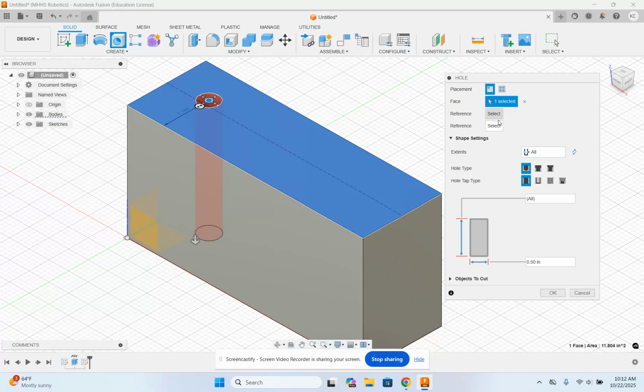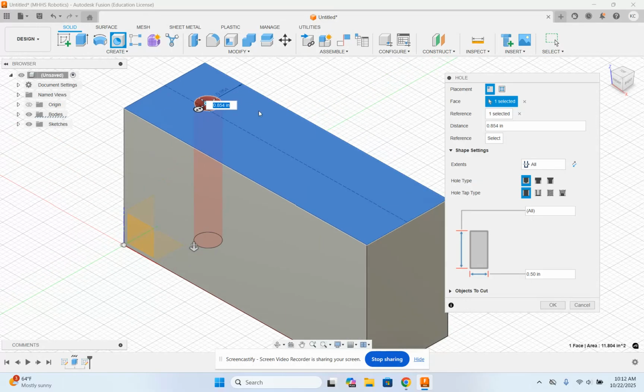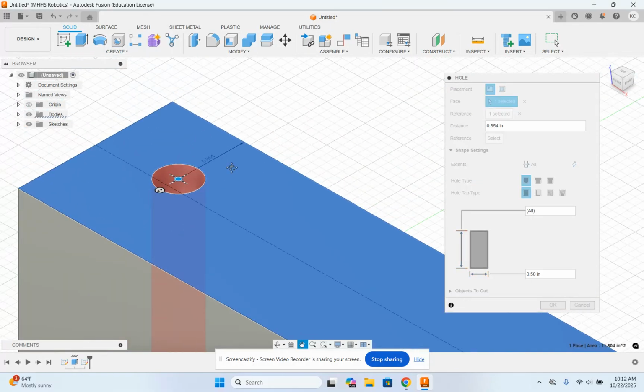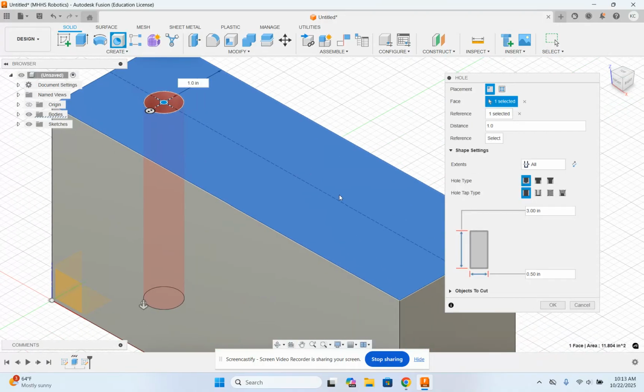The second step is these reference sides. We need to reference how far away from these sides. So I'm going to click on the first reference, click on this edge, and it needs to be, if I look at the arrows, right, zoom in, it needs to be 1 inch away, right, so that it's on that line. And I drew that construction line earlier so we could make sure. There we go. And that looks good for a distance over.